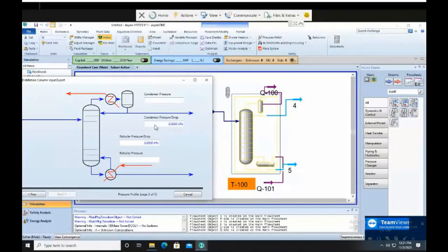pressure across this. Okay, so the pressure across the distillation column will be decided by what is the pressure at the reboiler and what is the pressure at the condenser. So in here just now it was 7.2, right, 7.2 bar. So in distillation column, you have to be very careful because you know that the driving force of flow is pressure.